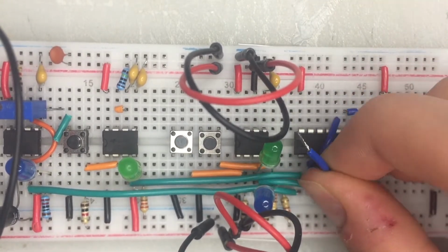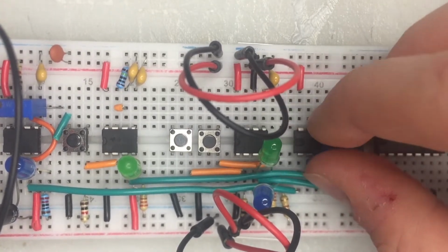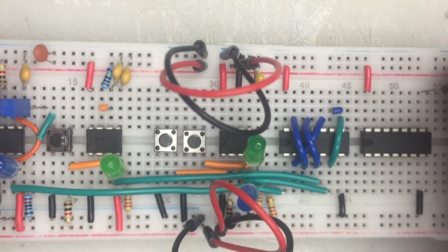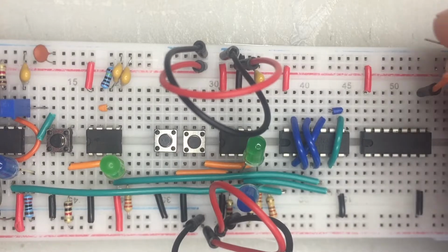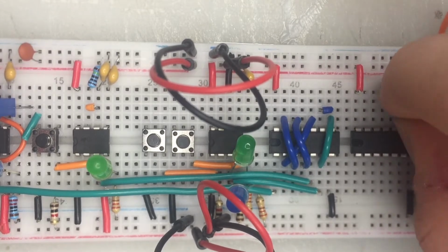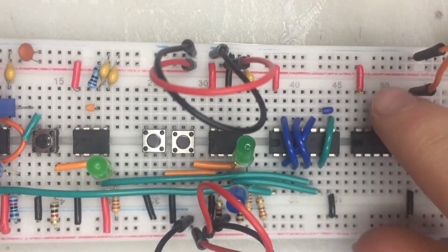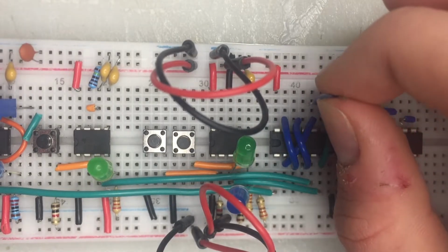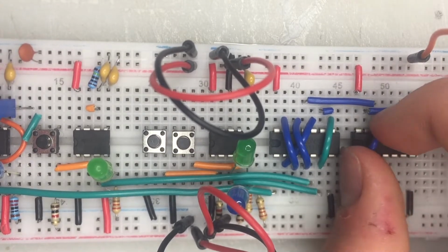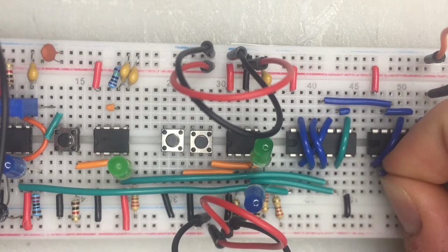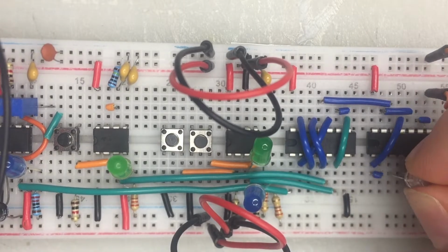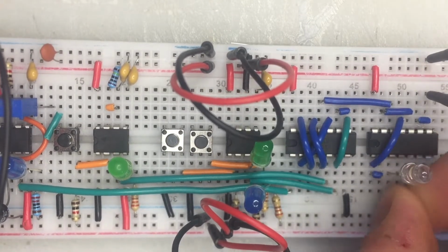And now I'm going to connect the output of gate 1 to one of the inputs of gate 4, and I'll do the same for gate 2. Now I'm going to plug a jumper lead into one of the inputs of gate 5, and this is going to serve as the halt line. And now I'm going to connect both inputs of gate 5 together. Now I'm going to connect the output of gate 5 to one of the inputs of gate 6, and the output of gate 4 to one of the inputs of gate 6. Now I'm going to connect the output of gate 6 to one of the inputs of gate 7, and now I'm going to connect both inputs of gate 7 together. Now I'm going to connect the output of gate 7 to an LED that's connected to a 220 ohm resistor, which then goes to ground.